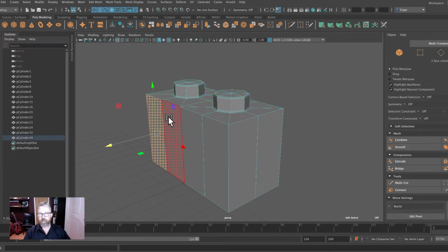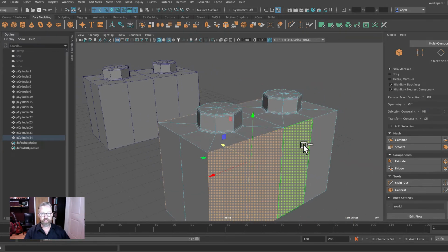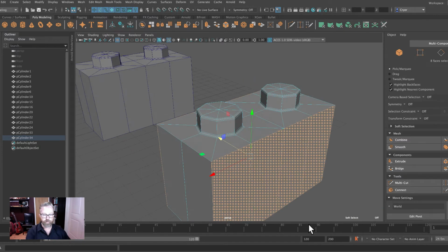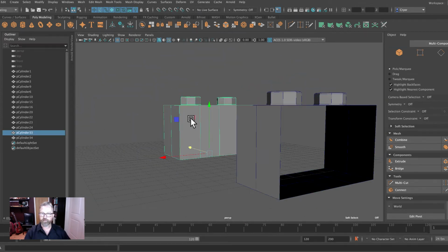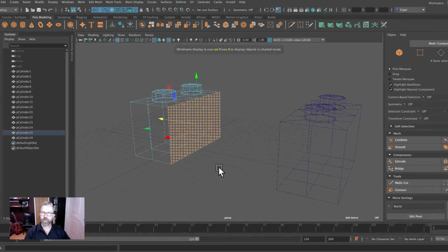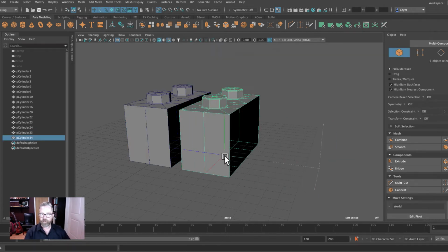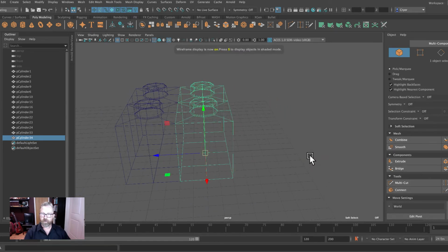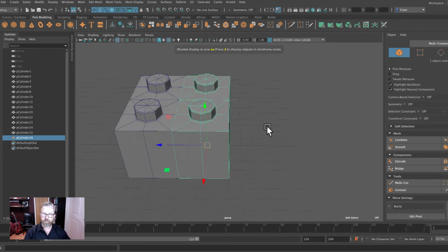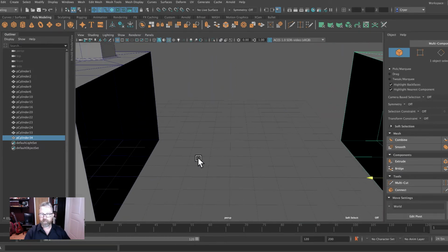In this case, let's create a hollowed version, a see-through version. So we're going to delete the faces on both sides. We'll hit delete. So now we have a see-through version. And as long as this is sitting out here, let's go ahead and delete these faces, 4 key, to make sure you've got a clean selection. We'll hit delete, and we'll set this back, holding the grid X key to grid snap that. If we take a look there, we've got those two pieces. This one is completely hollow, and then this has the faces that are facing deleted.